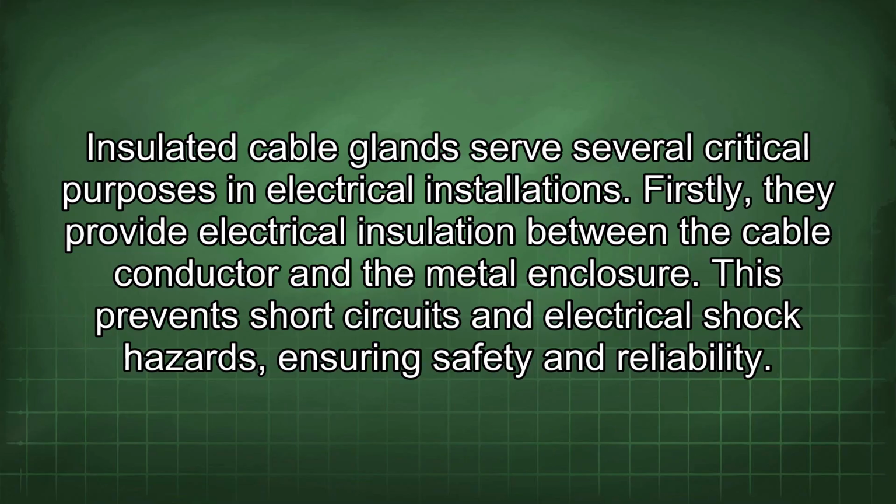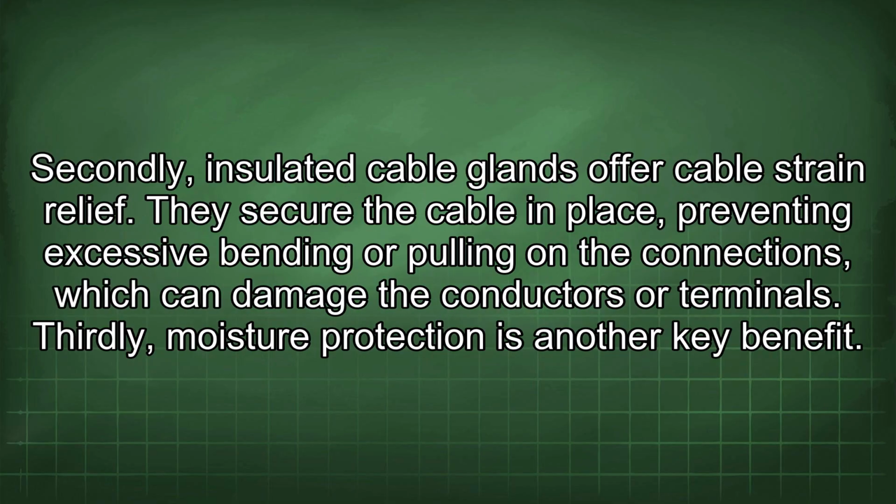Insulated cable glands serve several critical purposes in electrical installations. Firstly, they provide electrical insulation between the cable conductor and the metal enclosure. This prevents short circuits and electrical shock hazards, ensuring safety and reliability. Secondly, insulated cable glands offer cable strain relief.